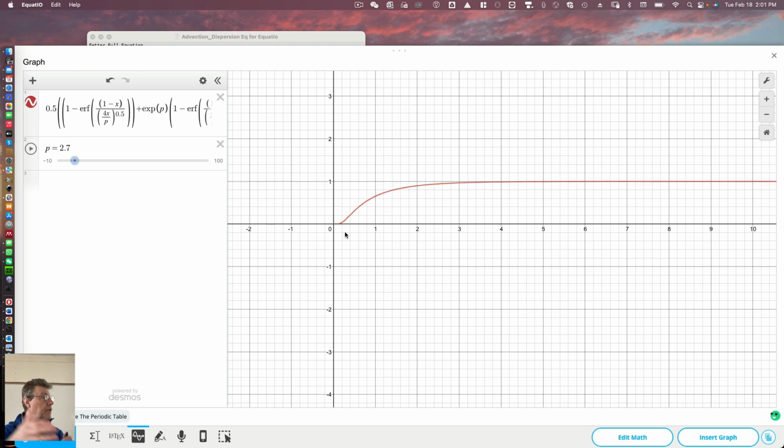You'd know within the core what your advective velocity is because you're applying a flow upstream condition to flush water through it. So you could calculate the Peclet number. And by getting the points along a curve, you could get the best fit through those points, and the best fit would give you a Peclet number.